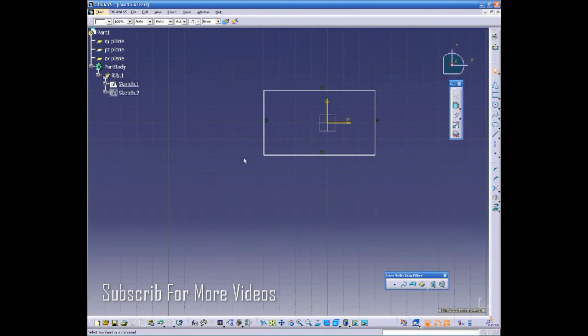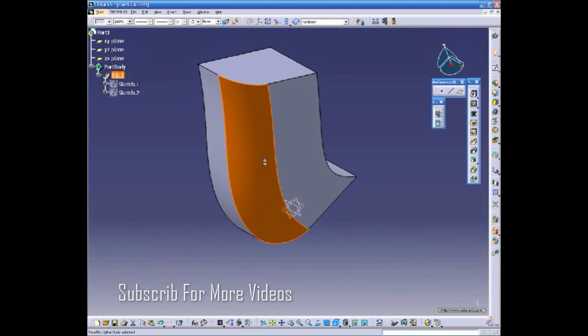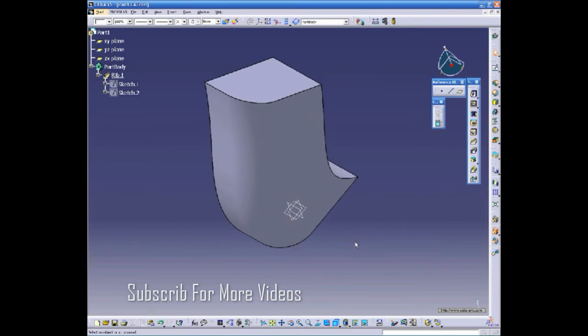Double-click Sketch 1. Add corner to the rectangle, and then exit the sketcher. As you see, the corner is added to the geometry automatically. One more time, double-click Sketch 1.